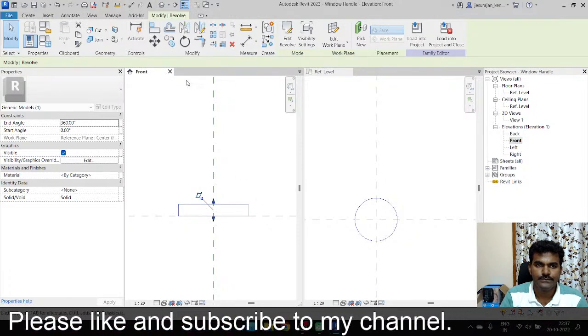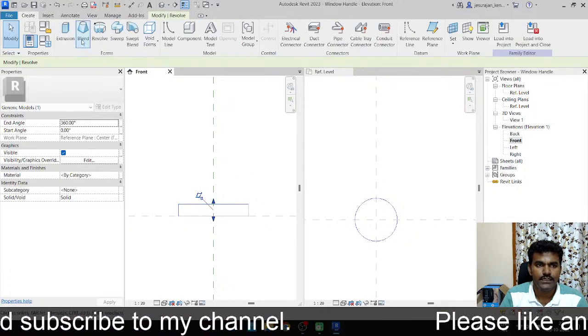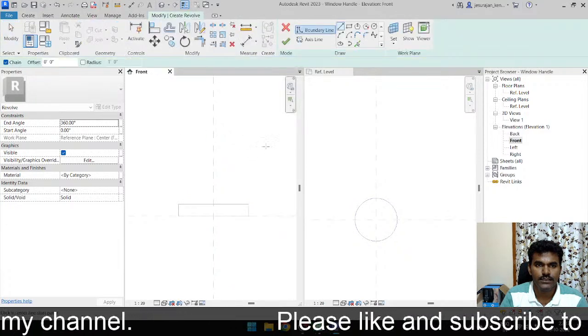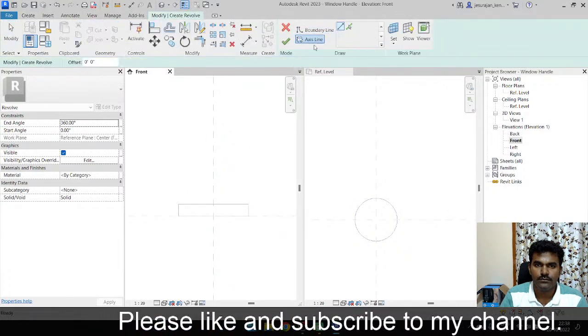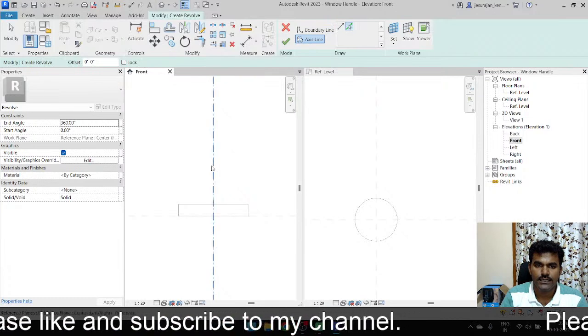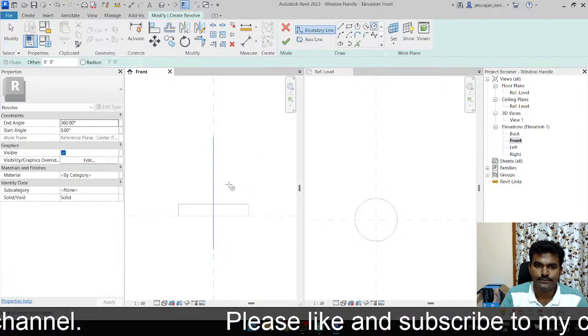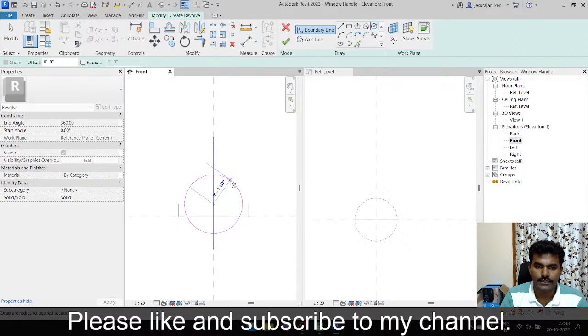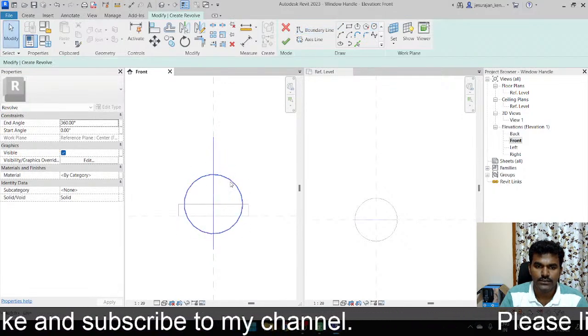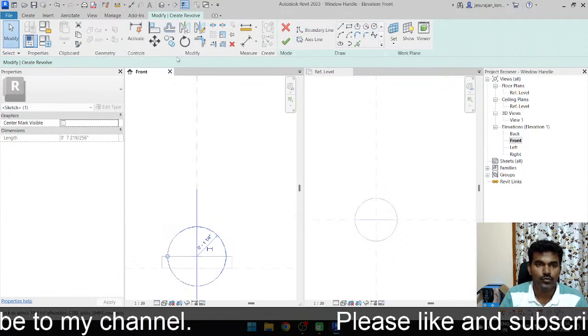Okay, go to create, take blend again, no, revolve, take axis line, select this line, draw boundary. You have to draw half boundary. Just move.